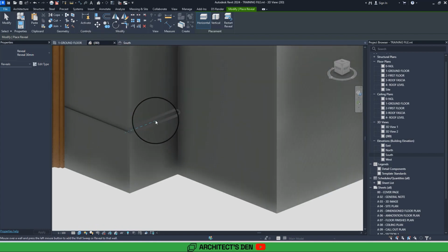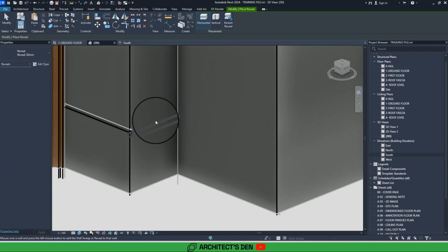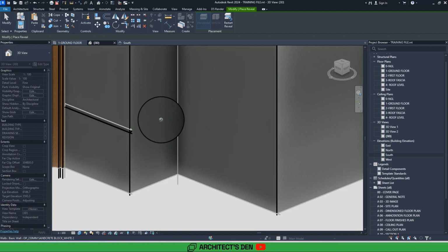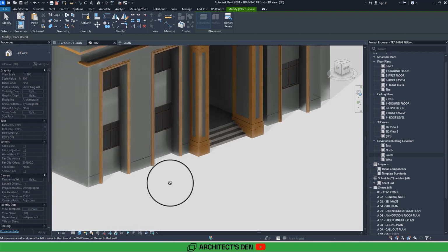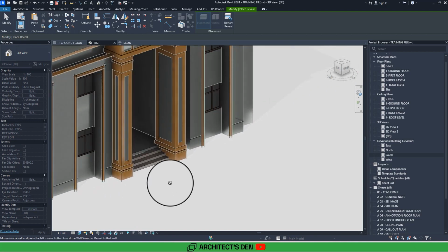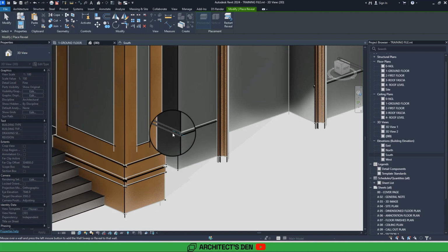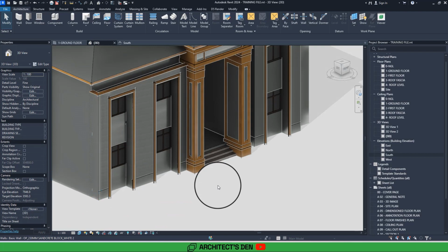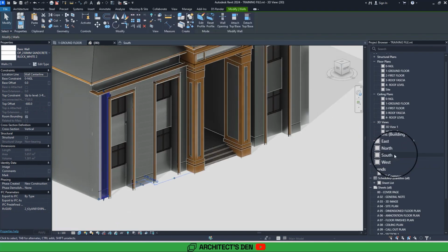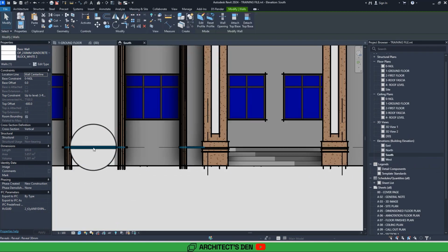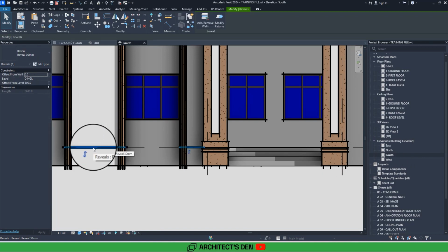It's still active. Now, when you are placing a reveal and you get to a point where the reveal is before, a dotted line shows. So I'm just going to click this on this face. There is a lag between when you place the reveal and when the reveal finally shows up, but not a serious lag. Just wait a second, you get it. So now I've placed the reveal all on this level where I want it. I double clicked on the wall and was trying to select the reveal, sorry. I can go back to my front elevation. Make sure I'm selecting the reveal like it shows now.